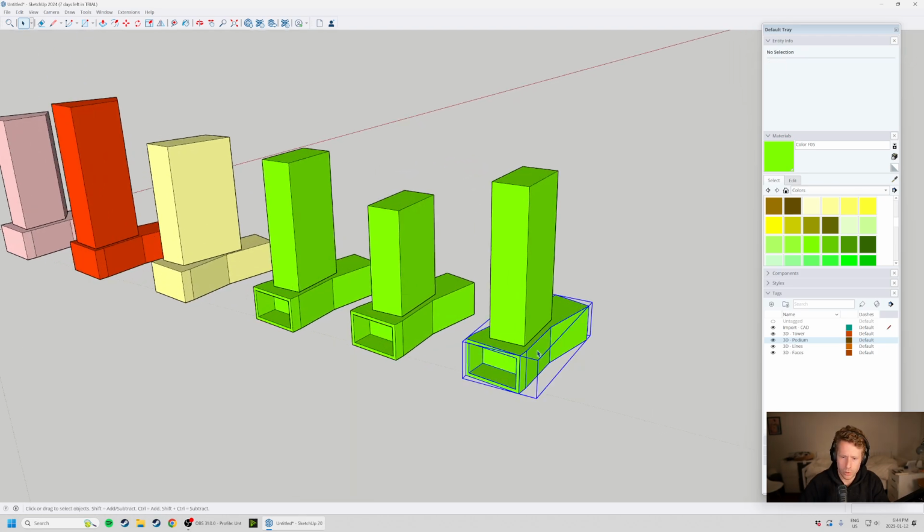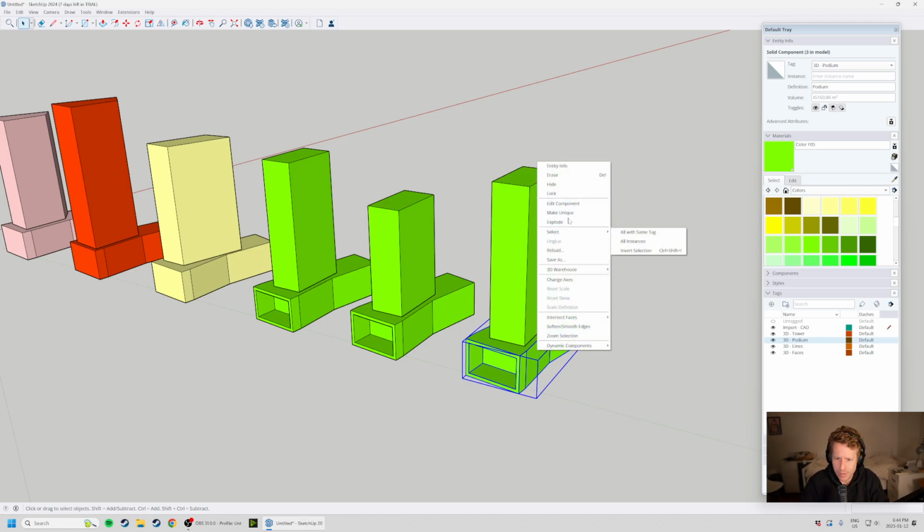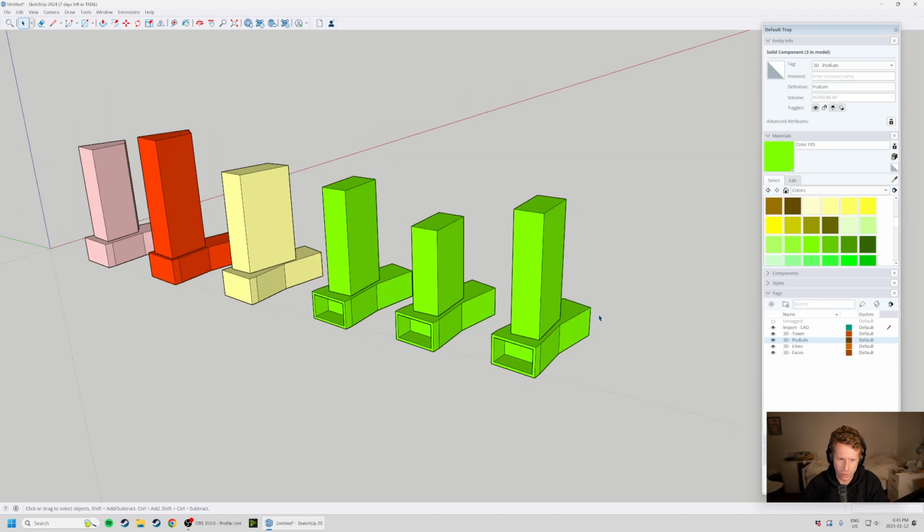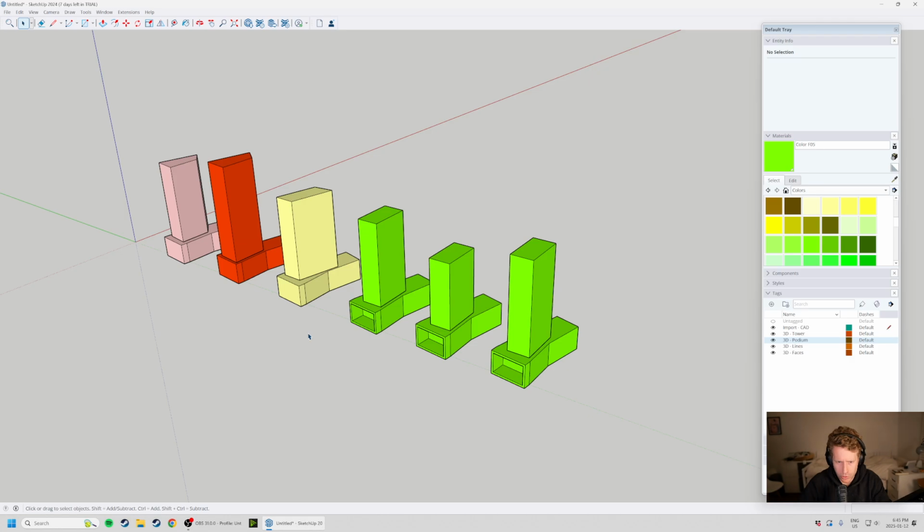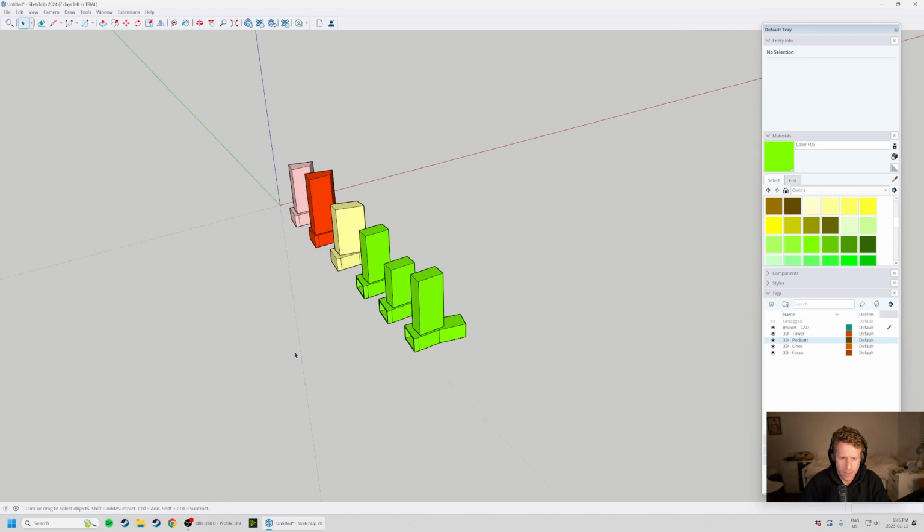One thing you might want to do is if you've got a component that you like the way that it's shaping up, but you want to create a little bit of a change, we can right click and hit make unique. Make unique will create a sub version, a subtype of that component that you've created. So this is really more of a design tool I should start with. You totally can use it just to get some ideas out.